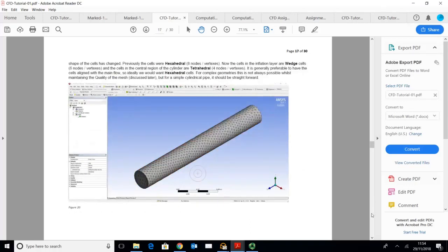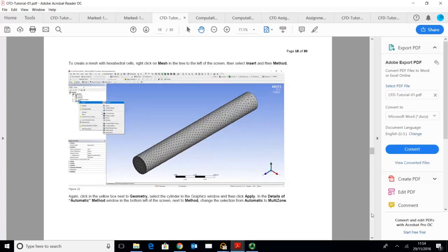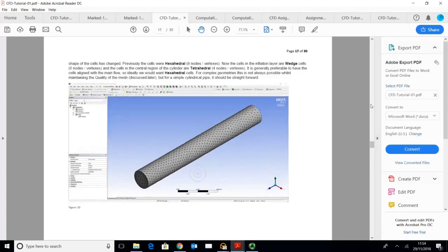You could obtain a refined mesh depending on the physics problem that you have, because for a pipe flow problem like this, you know that you need a refined mesh, or a mesh that can resolve the wall functions. Therefore, you need a higher grid resolution near the wall, and not that high grid resolution in the center.